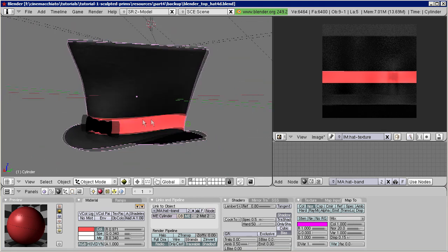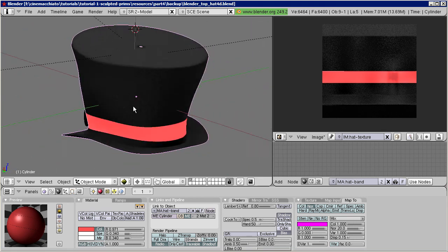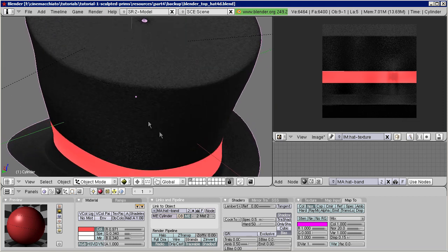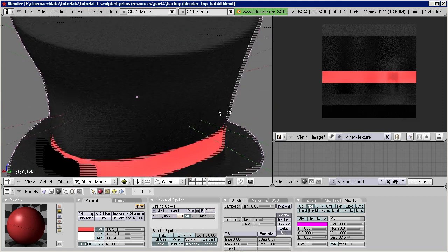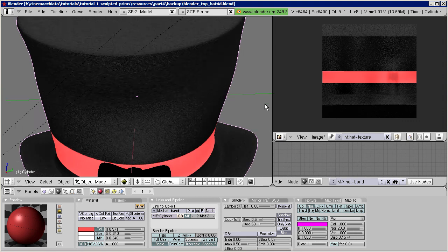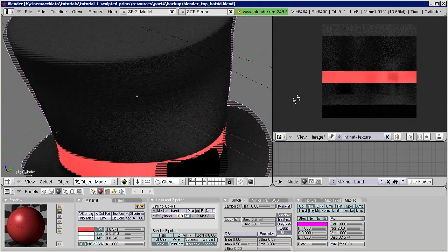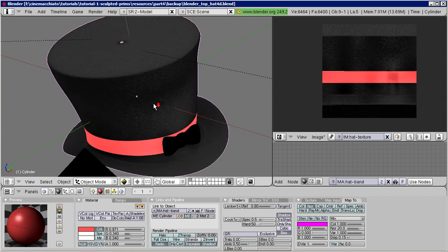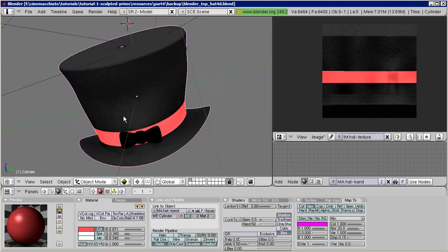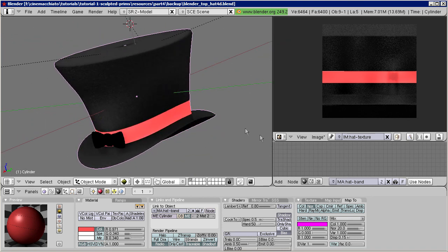However, we can get a bit adventurous, and try to use this map as displacement map. Remember that the baker will first apply the modifier stack before baking. Hence we actually have 32 x 32 faces available for the displacement. So reduce the NOR value to something below 2. And enable the disp button in the Map 2 settings.